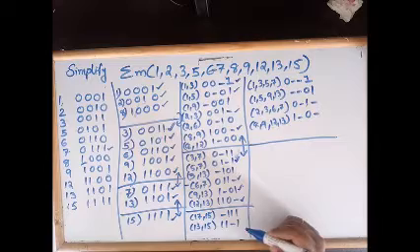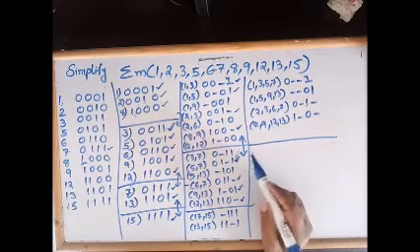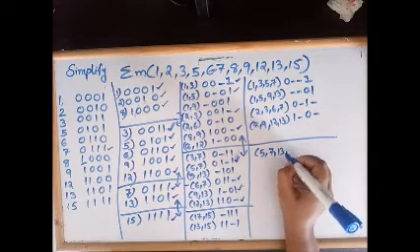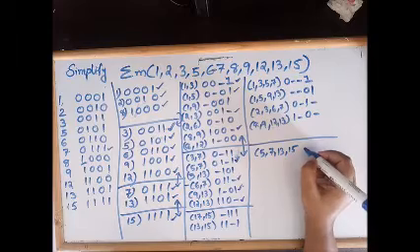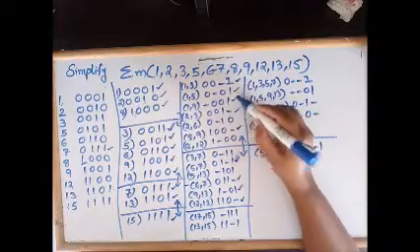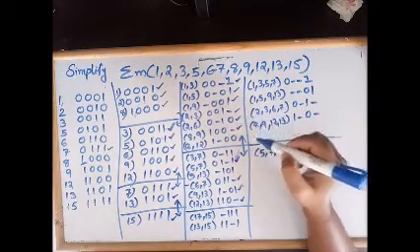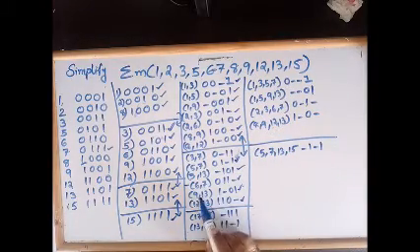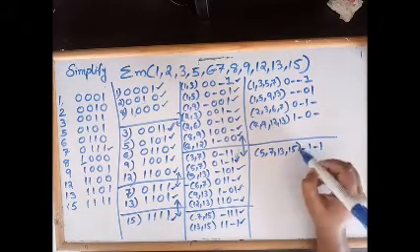When you combine the next two groups, you will get 5,7,13,15 with dash 1 dash 1, and we already took 1,5,9,13, then we took 2,3,6,7, and 8,9,12,13 is also there, then 5,13 is there, and 7,15 is there, so 13,15 is in there, so we took all the minterms.